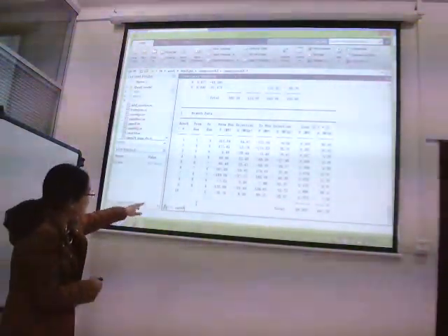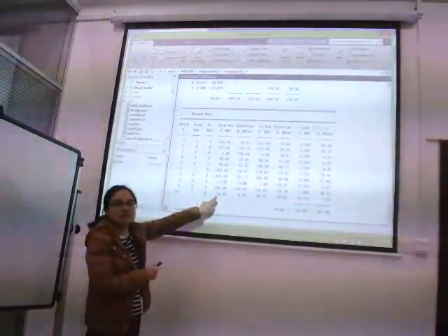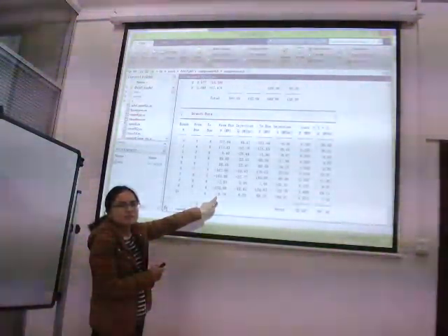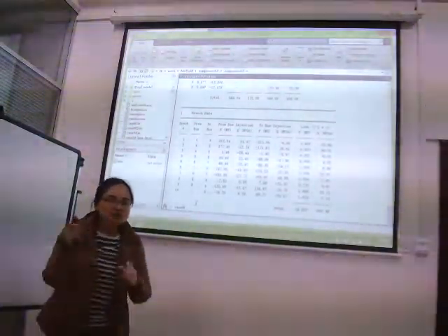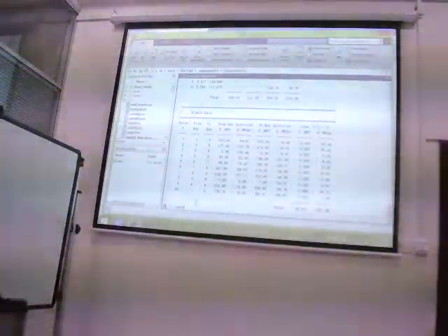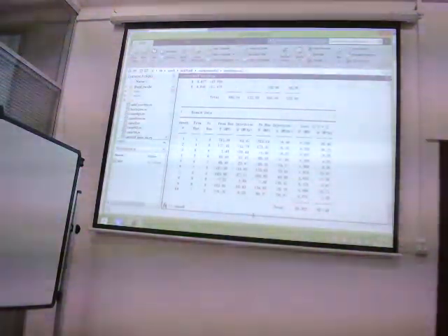Now let's have a look at here. Why is this value negative? For this generator 1, our power flow is just from generator 1. For this one, this is the opposite direction, a different direction. You understand? It is coming from 5 to 7, but it's listed as 7 to 5.